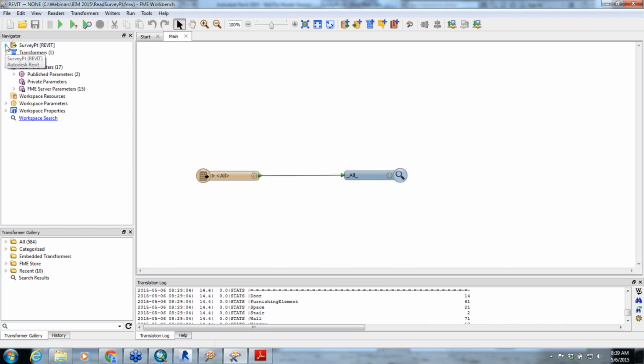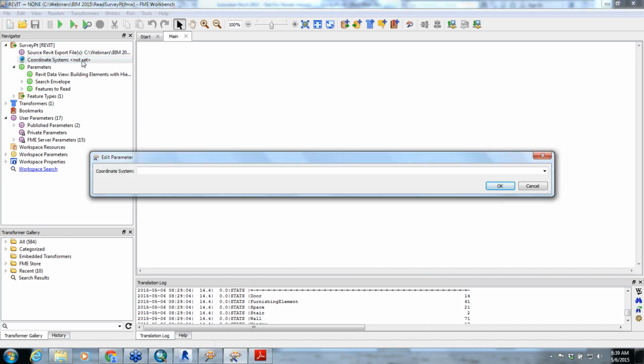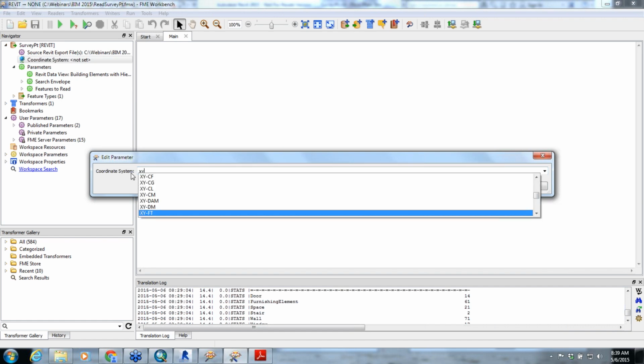I should point out that the coordinate system that we're going to create, even in the case of these survey points, is that sort of custom coordinate system based around that project origin, based on that location setting. In this case, that is not what we want to use because we've got the survey point that's located on another coordinate system. However, in FME, we make it really easy for you to override the coordinate system. You know it's some UTM zone, so you can set it to UTM here, you can set it to state plane, or if you don't know, you don't want to have that automatically generated coordinate system, which is wrong in this case, you can just pick an arbitrary one.